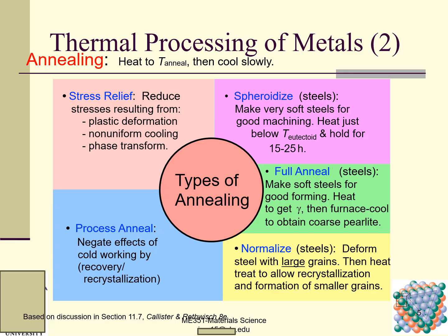Another one is process annealing, which negates the effects of cold working by recovery and recrystallization. So this slide shows different types of annealing and how to carry them out. I hope you understand all of these different types of annealing. You do not need to memorize these, but you need to understand.